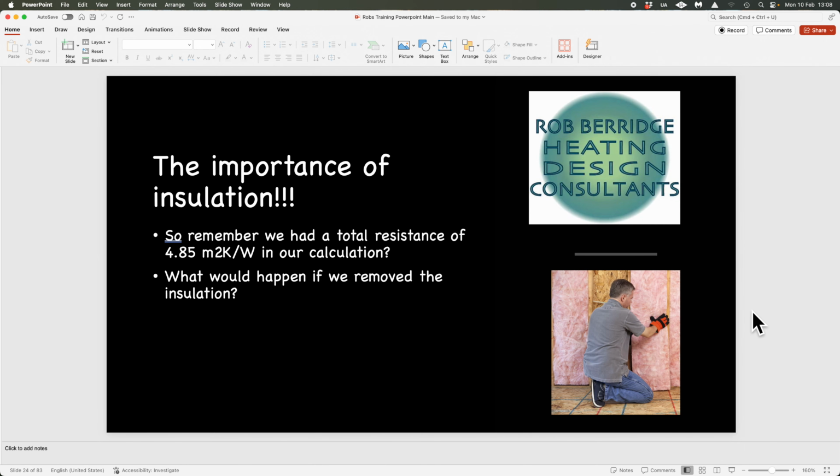And if it is polystyrene balls, then I would do one or two things. You've got to try and maintain the continuity of that insulation. That is the most important thing that you can do, and I'll show you why in a minute, with calculations of how much heat we can actually lose out of these things. So what I would do is take a bit of that insulation that guy there is demonstrating, they're just cavity wall bats that you've got there. You take a piece of that and make it into like a 4-inch gasket or something along those lines.